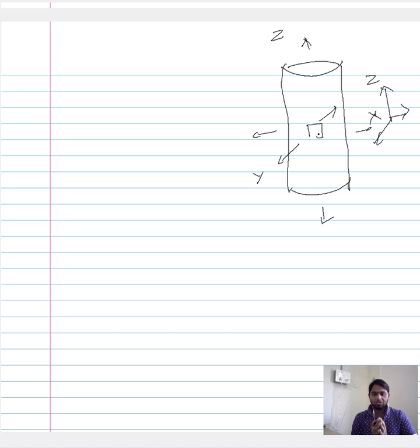So there is a point in our desired plane, and we want to know what components we need to describe the mechanical condition experienced by that point when the three-dimensional system is experiencing a triaxial tensile loading. For that, in the previous lecture, we constructed this point, or this element, as a cube.